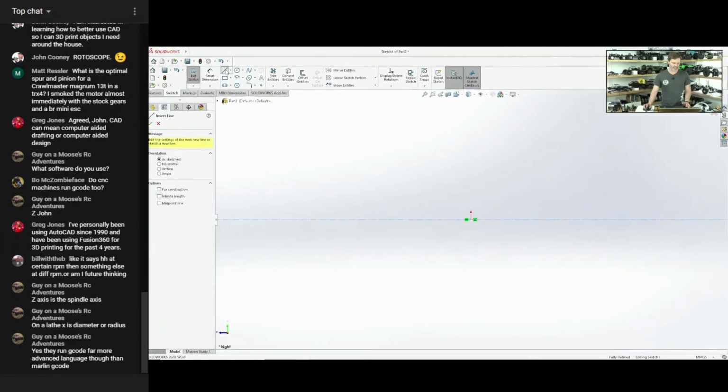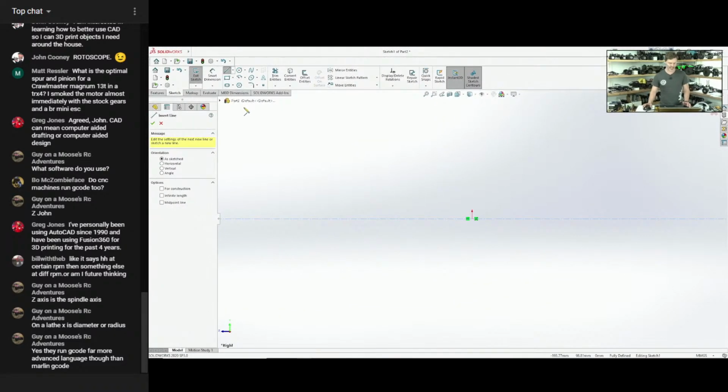The next thing I will need is another line, and the simplest way is to deselect and reselect the line. With the motor housing, it really doesn't matter which way it's facing, bearing pocket on the left side or on the right side. If this was going to be made in a machine with at least 2 live tools on the back side, it's going to be able to do it either way. But if it only has live tooling on the front side, not on the subspindle side, then we would have to be careful which way it's oriented. Of course, the CAM software could flip it around, or maybe they're doing conversational, and I'm getting sidetracked with things that don't really matter.